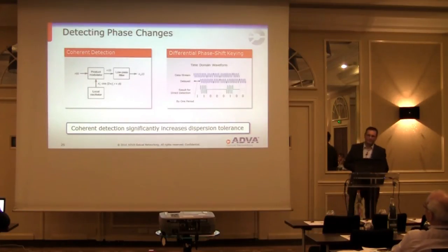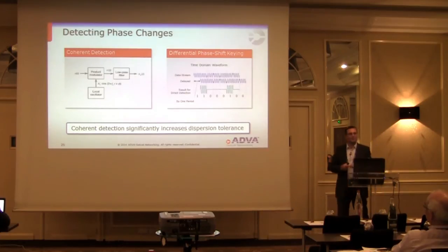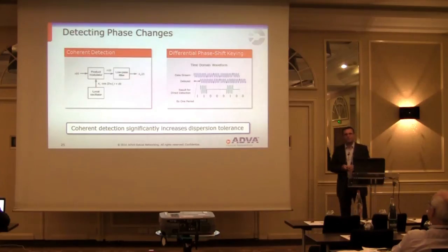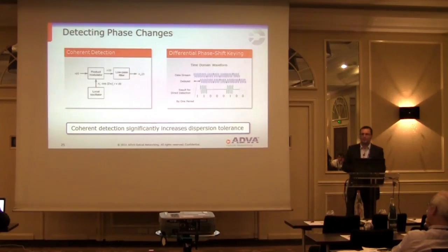So using this interesting technique, we can easily figure out where are the ones and where are the zeros without coherent detection. But still, this is more complicated and more difficult to build than the on-off direct detection where you just look at light on, light off. But if you want to use more complex schemes here for modulation, we have to go through that.